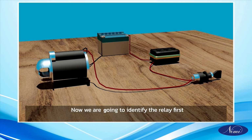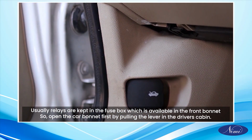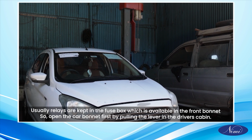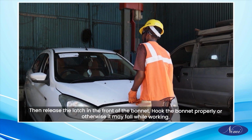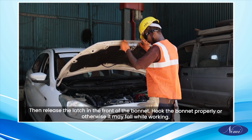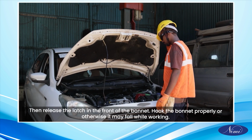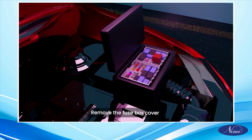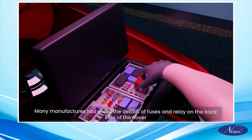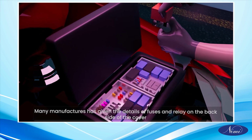Now we are going to identify the relay first. Usually, relays are kept in the fuse box, which is available in the front bonnet. So, open the car bonnet first by pulling the lever in the driver's cabin. Then, release the latch in the front of the bonnet. Hook the bonnet properly, or otherwise it may fall while working. Then, locate the fuse box. Remove the fuse box cover. Many manufacturers have given the details of fuses and relays on the back side of the cover.